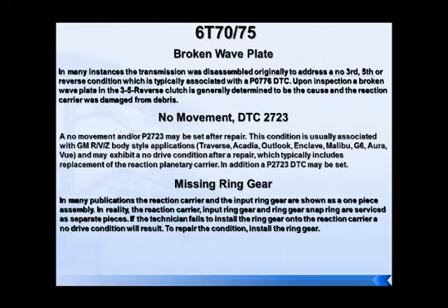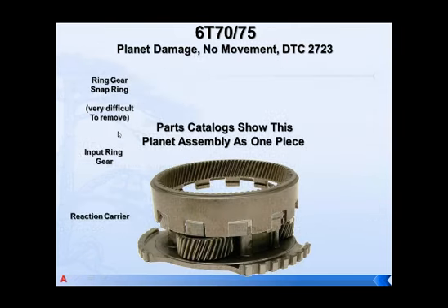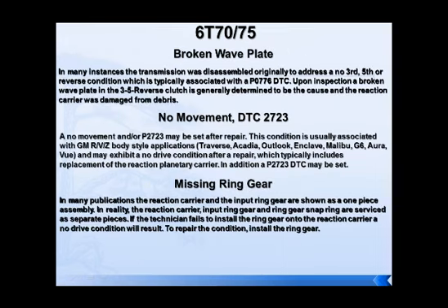All right, you break that wave plate. You broke the wave plate itself, and now you have another little issue. You may end up with a code 2723 set. You may end up with a no movement condition. Here is why. We've had this happen several different times.